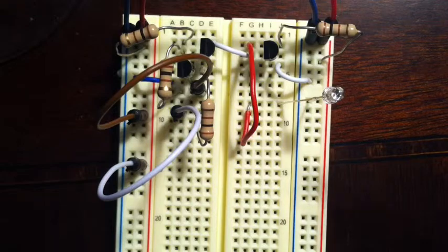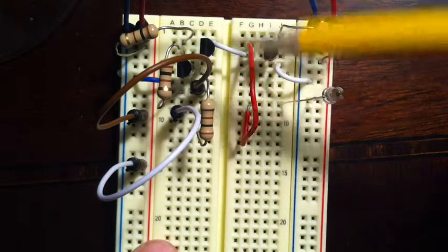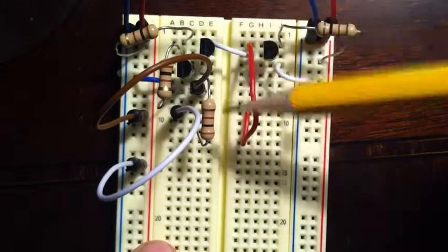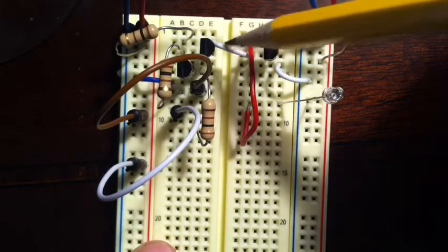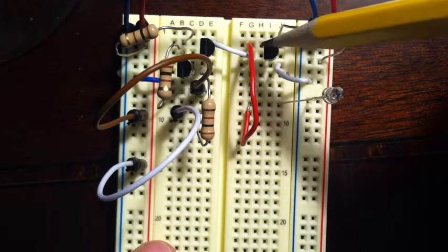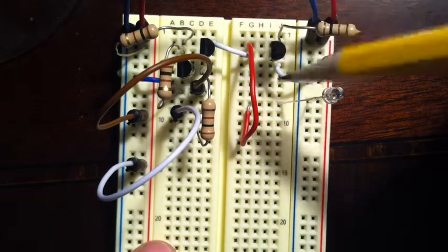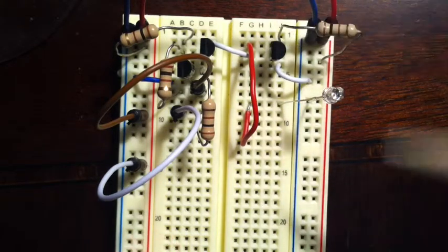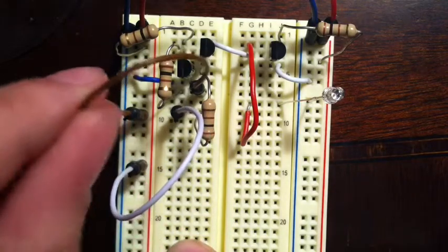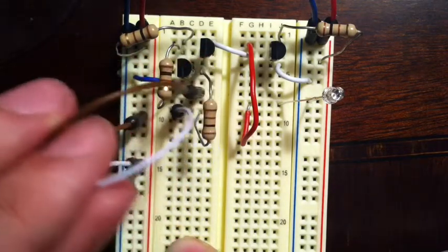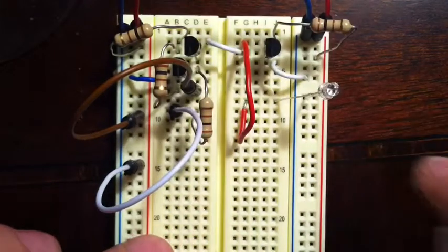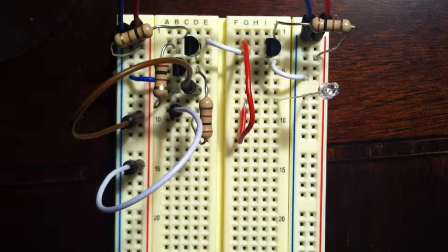Alright, so this is the first AND gate that I made. As you can see on this side right here, this is the AND gate, and the output comes from this white wire down, and then I just NOT it using this gate right here. These are my two inputs, and they're just hooked up to the AND gate, and then all you have to do is NOT the output. So I'll show you guys what it looks like.